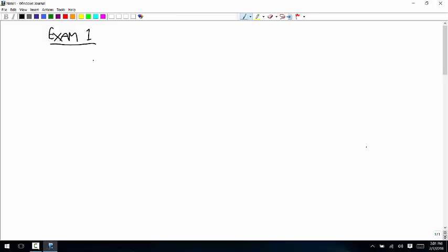If you have your units for Young's modulus in, say, pascals, you know, what was the number, 62.5 gigapascals, okay, so you use that to get, and whatever this is, that doesn't have units, you use this to get the compliance matrix. Then when you write your Voigt stress, that has to be in pascals too. If it's not, everything goes haywire.